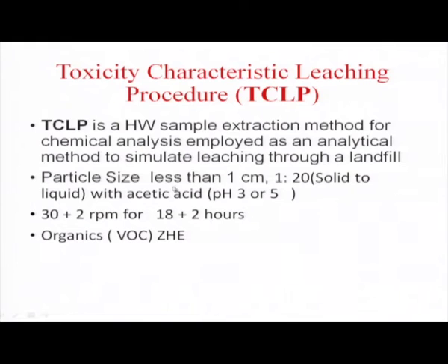Okay. And the test is usually conducted with leaching with acetic acid, employing a pH 3 or 5. Suppose the waste pH is highly alkaline, you have to go for a pH 3 based acetic acid solution. Suppose it is near neutral, then you can go for pH 5 based acetic acid.